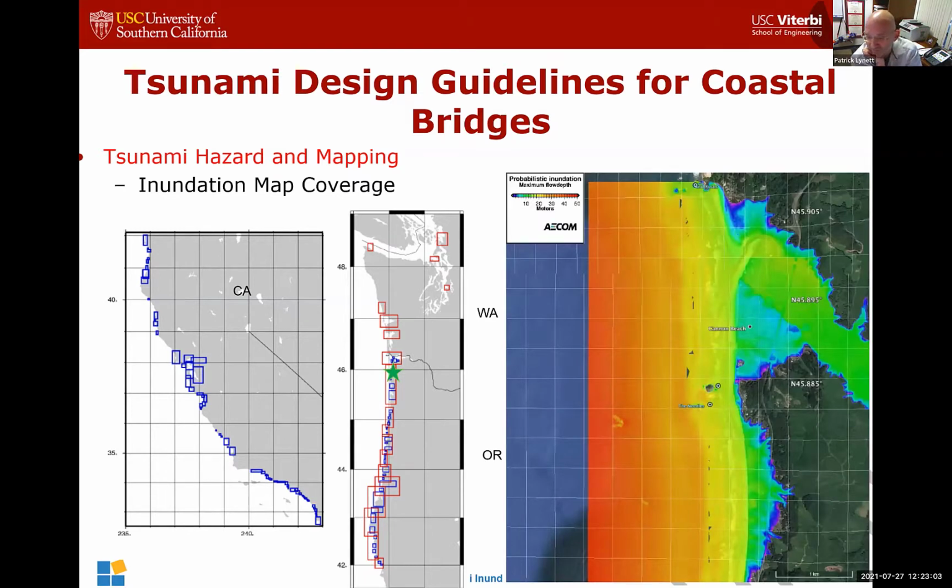That inundation results for all these different grids is going to look something like this. So this is just an example of this flow depth. It gives you the flow depth at the 975 level for this particular area. From the modeling, we have these maps of flow depth, we have maps of flow speed, we have maps of something called momentum flux, which is useful for figuring out drag forces on buildings. All of these surfaces are included in the tool that Sylvia is going to introduce.